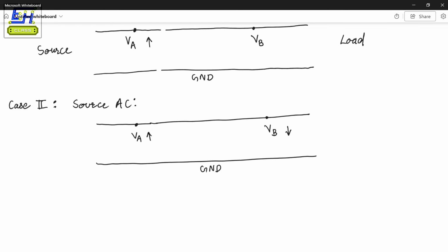But instead, what you can do is measure the RMS voltage, right? That is very important, and that is also the reason in AC circuits we always consider RMS values and not instantaneous values, because the current is oscillating, but still, if you take the RMS, that's exactly the actual power of that source or of that AC signal.